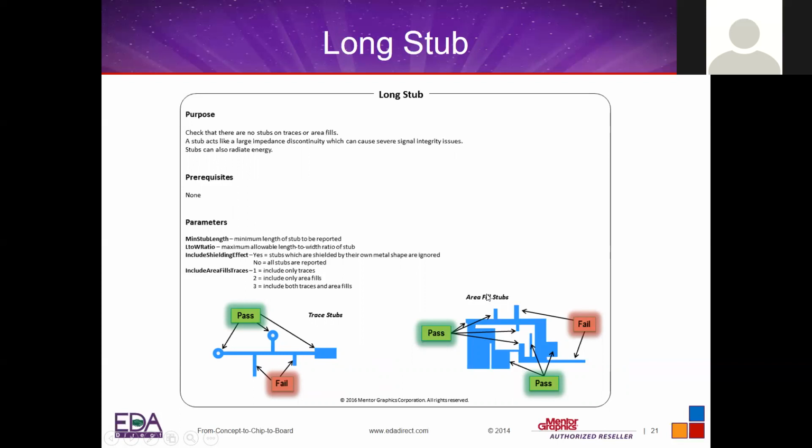Some designs may use resistor multiplexing. For example, what I mean is, one source, if you're running the board in this mode, then you populate this resistor, and it takes that path. And for a different design, you populate another resistor, and you depopulate the last resistor, and then the signal goes through that path. So they're using this like a mux-through resistor. And while that works on paper, in real life, when you are not populating the other components, those are stubs. And if those are clock lines, you will get reflection, you will get impedance discontinuities, all things like that.